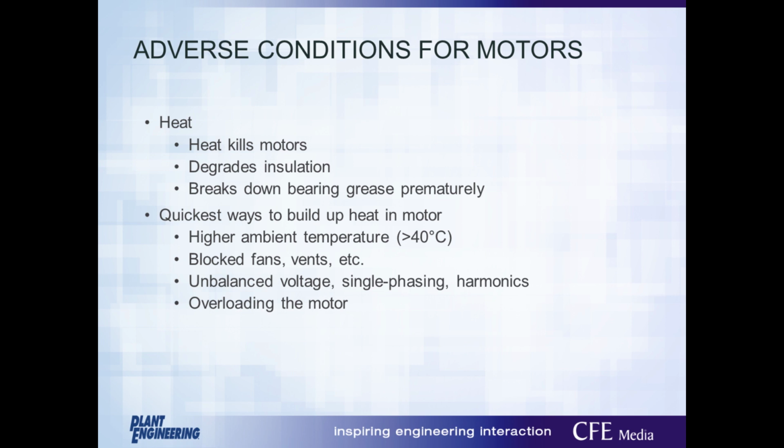So here's a review of a slide from where we left off prior to the poll question. Heat kills motors. For anyone who did participate in the webinar earlier in the year, maybe you remember that. That was kind of my main message, heat kills motors. If heat kills motors, this begs the question, what causes motors to heat up? High ambient temperature, blocked fans, blocked cooling vents, overloading the motor above rated load, and then, of course, power quality issues at the motor terminals.